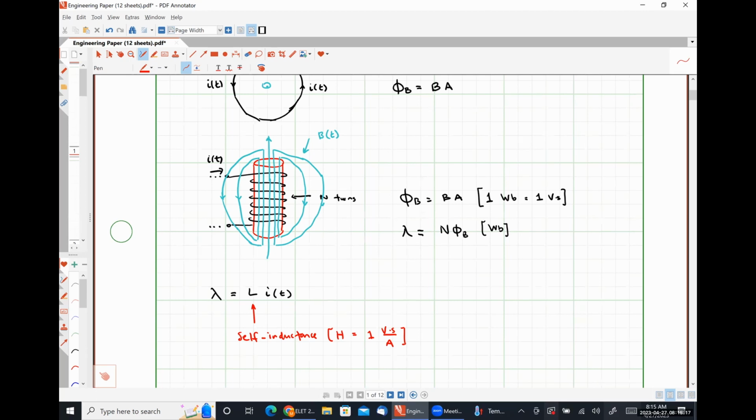So this is the exact same thing as the inductors that you would put in a circuit. They're literally just coils of wire. So we're more formally explaining what an inductor is. And we've gotten to the point of describing the concept of self-inductance, where our coil of wire is carrying some current, which generates a flux that passes through the same coil that is carrying the current. So self-inductance is the flux generated by I1 passing through coil 1.